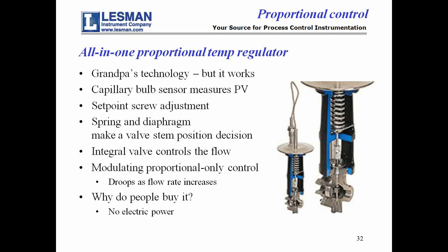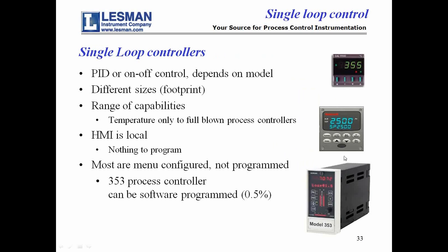Basically, though, there's a whole market out there of single loop controllers that do PID or on-off control, depending on the model. There are different sizes, as you can see from the pictures on the side. There's a whole range of capabilities. The one at the top is really a temperature-only controller, and the one at the bottom here is a full-blown process controller. The key to these is the HMI, the means that you interact with it and it tells you what's going on, is built right into the thing. There's nothing to program to get the HMI working. When you plug it in, the HMI fires up and it's just there.